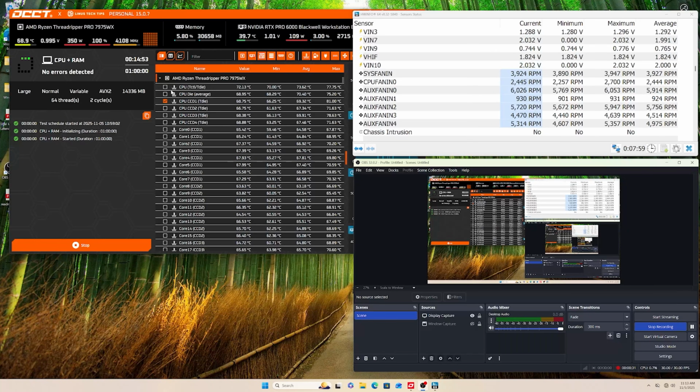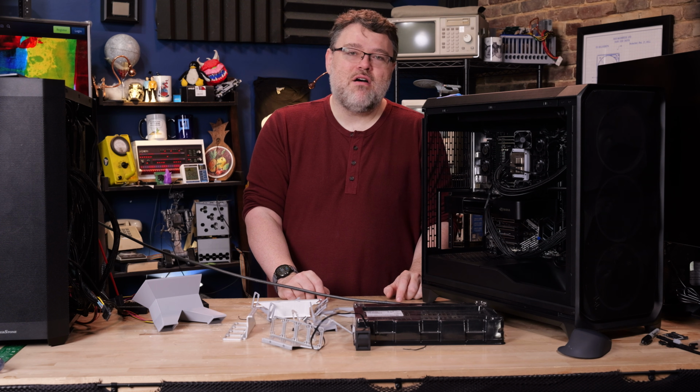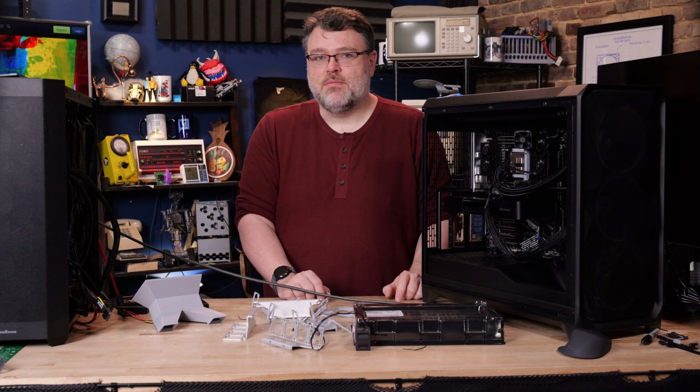Watch for silent throttling. Even if your throttling is working correctly, you may be hurting performance. I did a script using Intel's Memory Latency Checker utility to generate both an artificial load and monitor the memory bandwidth for signs of throttling. It's a great sort of one-two punch to do that because there wasn't something out there that really does that. DDR5 is powerful but harsh and unforgiving.